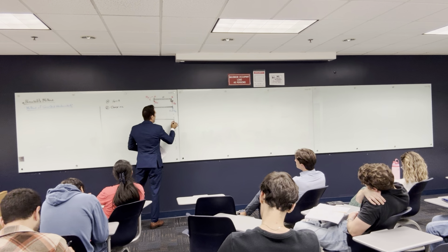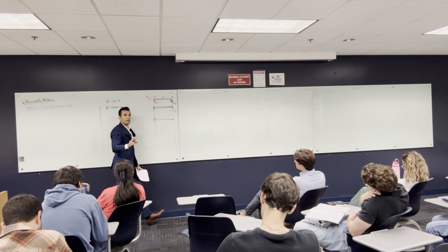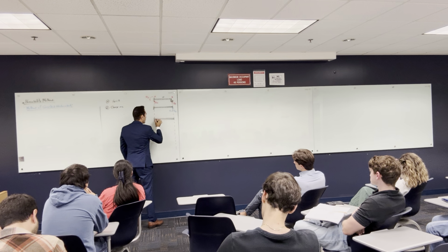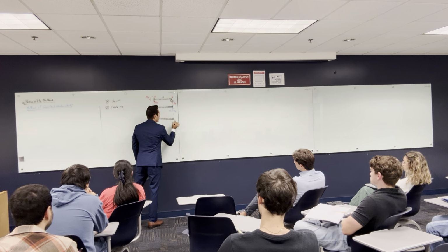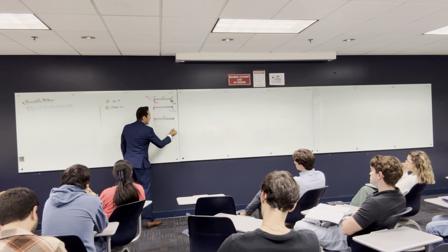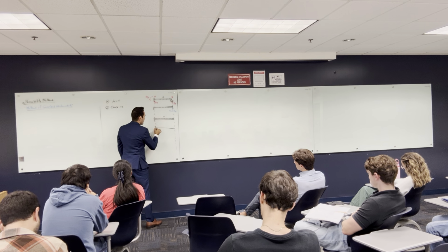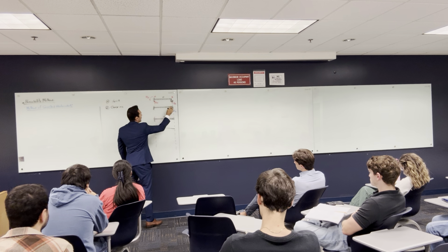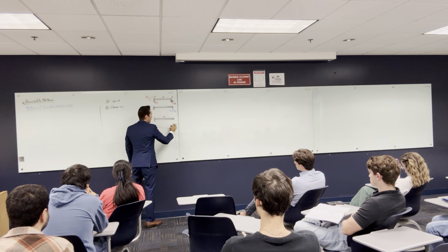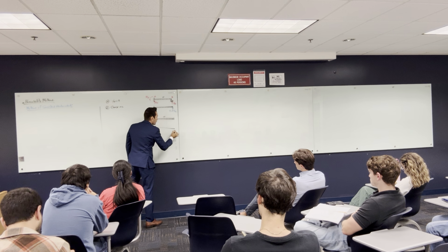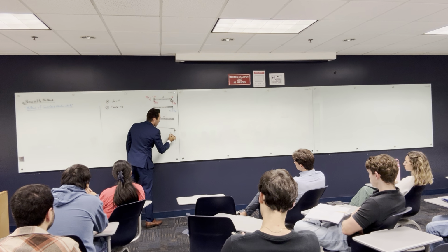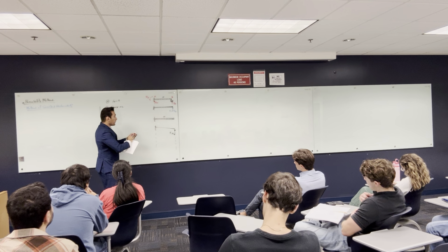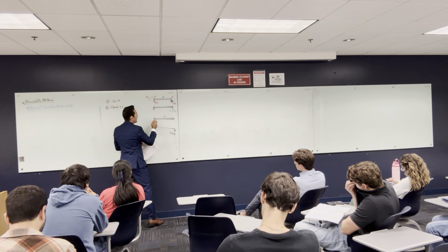All right? And what I'm going to do right now, I'm going to use the method of superposition. I'm going to take this distributed load W alone on this system, and the other system, this system, and I'm going to put this reaction, which is F equal to RB. So the deformation of the two systems, this one is going to make a deformation like this, right?